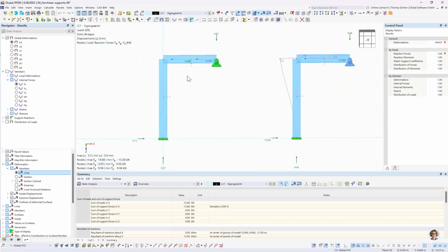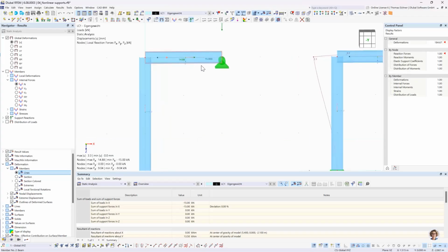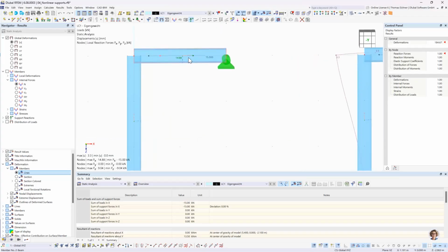The support direction looks in the positive x direction, but just as I mentioned, this is visualized as external force, and the force that really comes to that support would point in negative x direction, like the force we applied here. You see this 15 kilonewton?